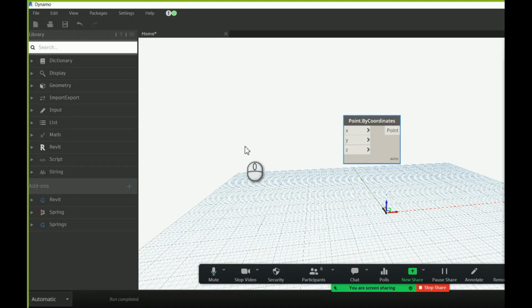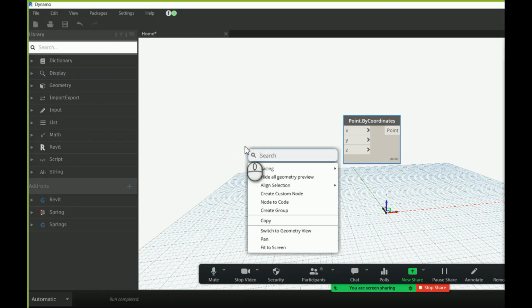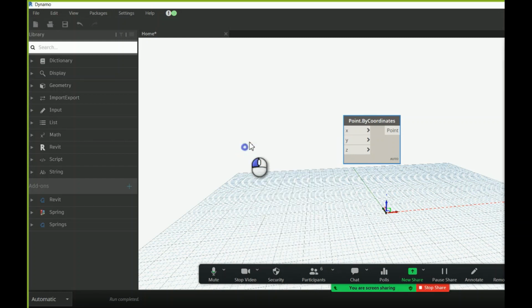Now, I will go right click and write, actually not right click, I'm going to go code block. So I'm going to start from 0. I will start from zero. 2 dots to 2. And then I will write 57, which is the amount of floors. 2 dots by stepping, or by using 6, which is the height of the single floor.